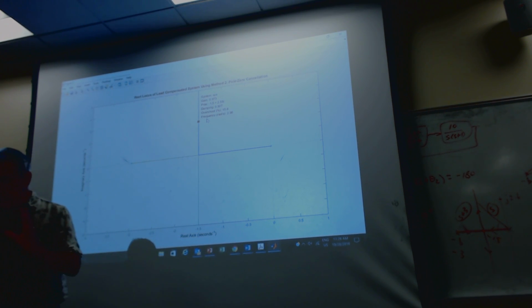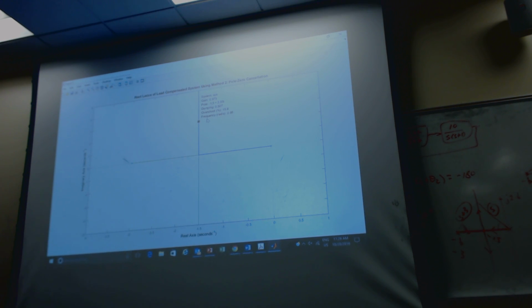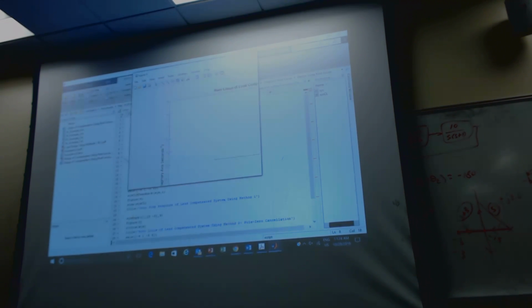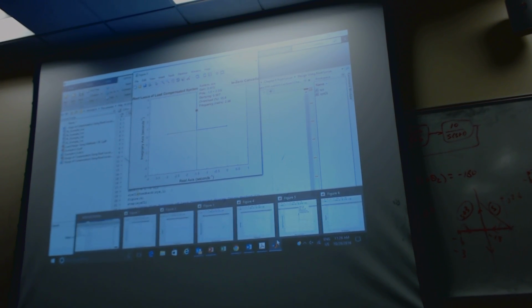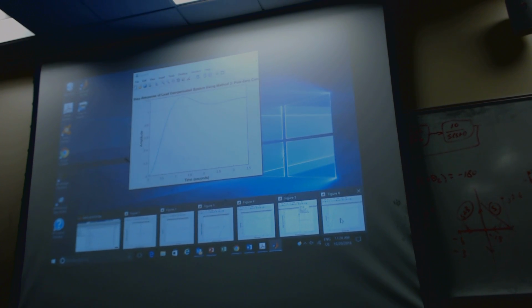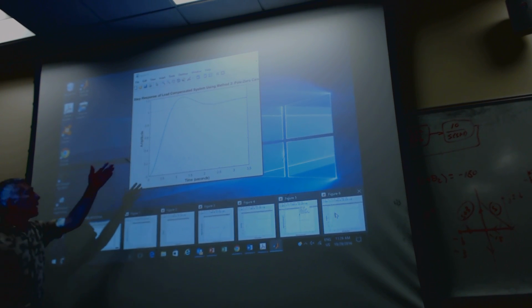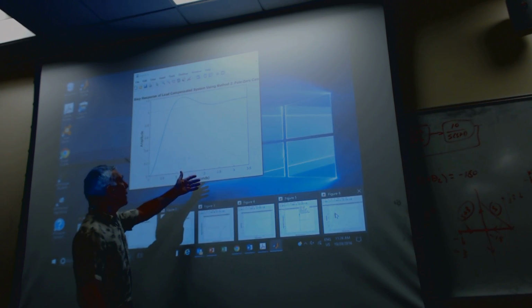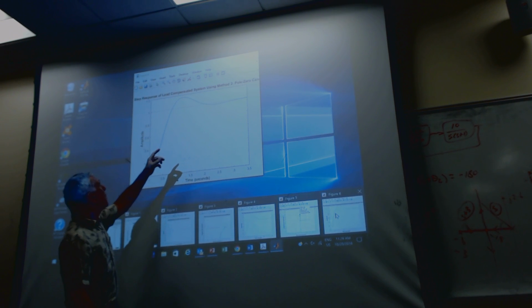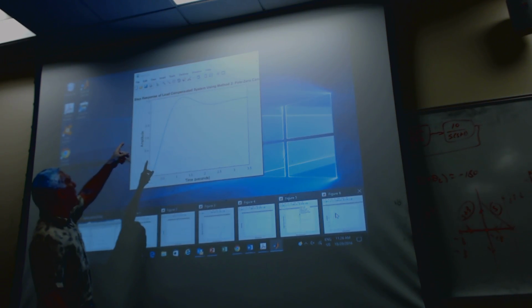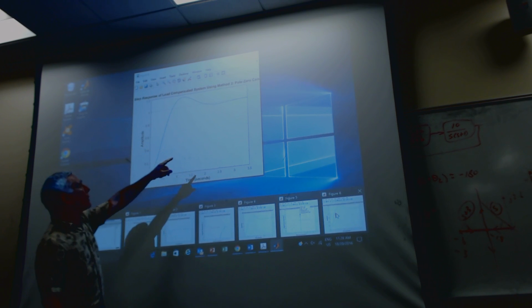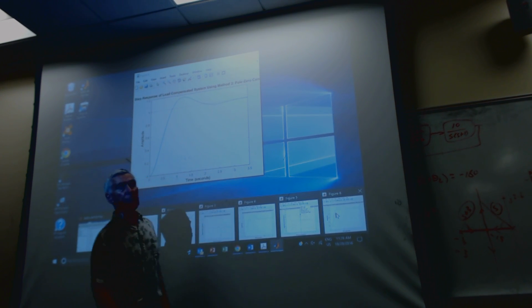It's not assuming any pole zero cancellation. And by the way, I just showed briefly what you would get for that case, the other method, and we'll go through it. And by the way, this one here shows the overshoot and the settling time that we get for the case of pole zero cancellation. So you get about 15% overshoot, and the settling time settles out in about 3 seconds.